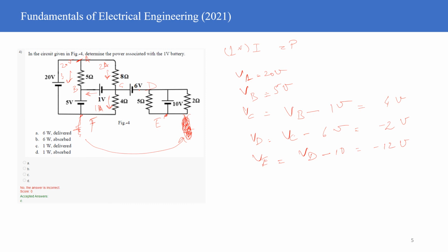All right. So no current flows in that particular branch, and therefore I can apply nodal analysis at this particular point. The nodal analysis will say that the current I is 2 amperes at this point I'm applying. This current is equal to 0, there is no current over here. So I'm writing my sourcing current, 2 amperes, as I plus 1 ampere, because this is flowing out and this is also flowing out.